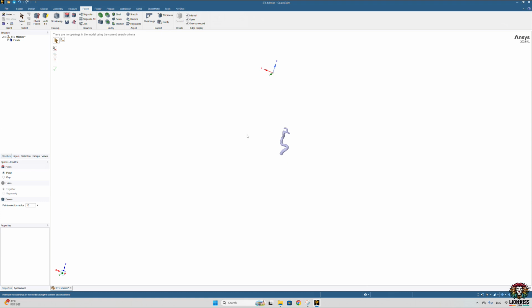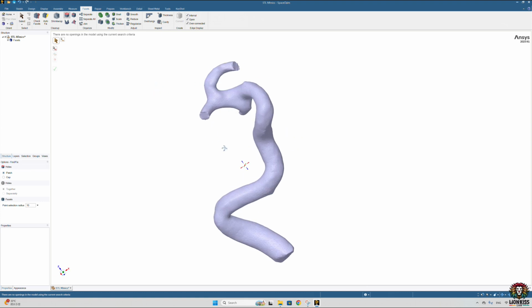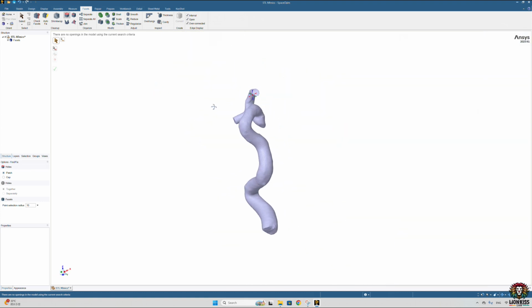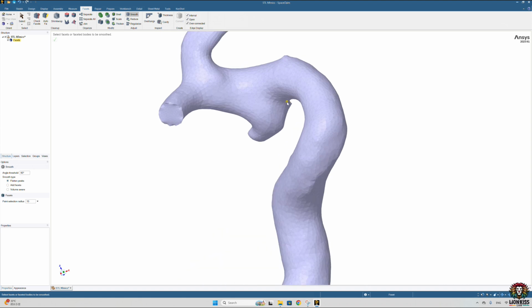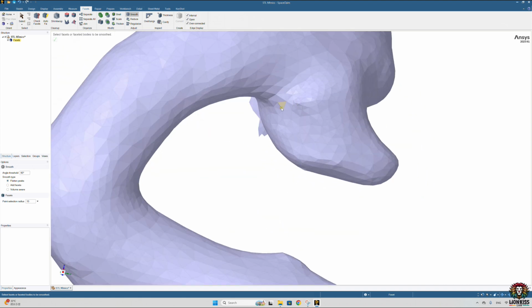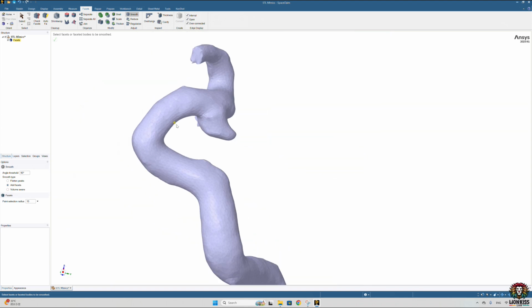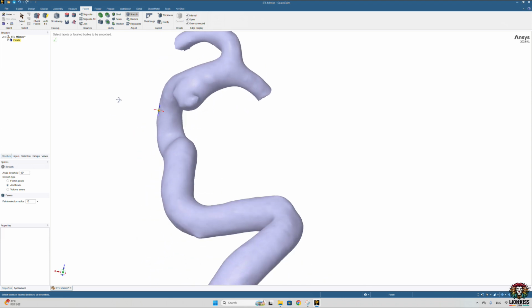This is our smooth one, but still the mesh is not that smooth. As you see, the outlet and inlet are not smooth. Now we're going for the smoothing, and there is flattening of the peaks. If you see this one, it is a very sharp peak, so it makes a flatten, and I use edit facet and volume away. I use the edit facet because it increases the facet size and the facet numbers, and it's more smooth. So I do one smooth, and you can see how very beautiful and very smooth it looks.